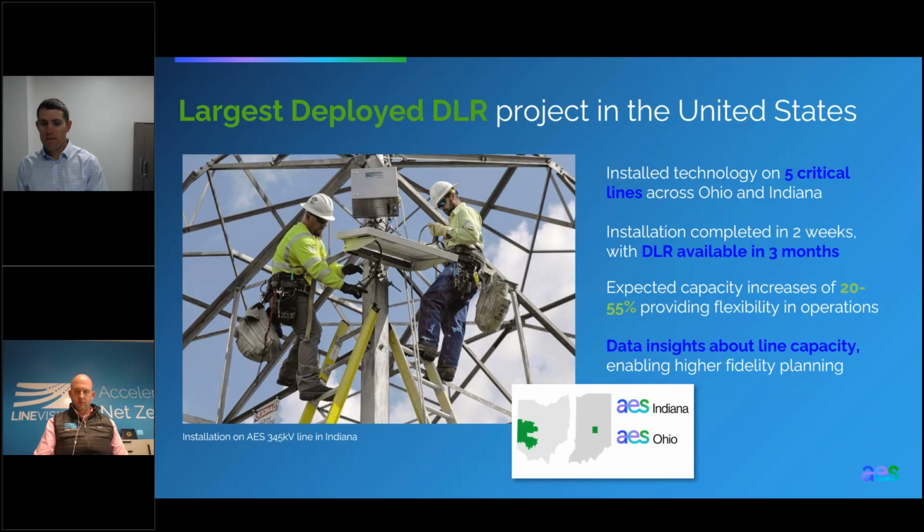So all 5 lines across both states were completed in 2 weeks, and you can see the installation there on the slide, right? It's done with ladders, hand tools, and a crew of 3 to 4 linemen. And in fact, our linemen got so good at this that by the end, they were putting one up in 15 minutes. So it's something that is very quick to install, and it's very safe.